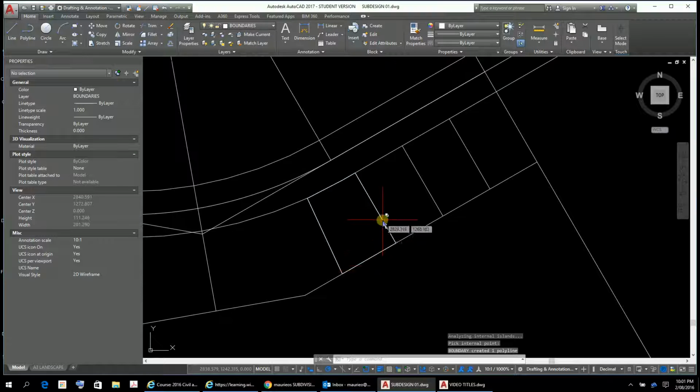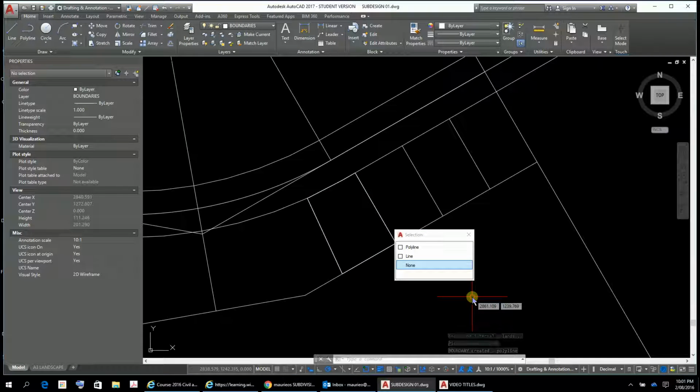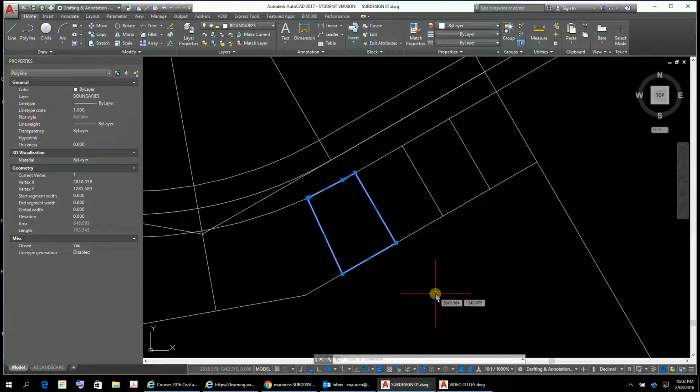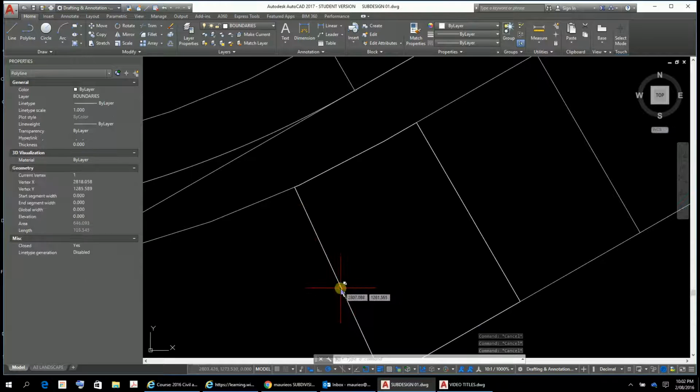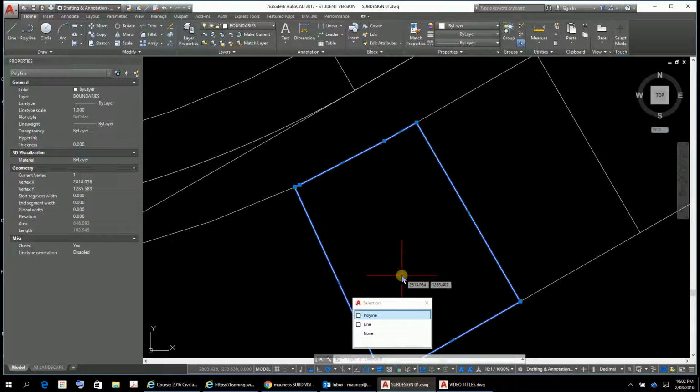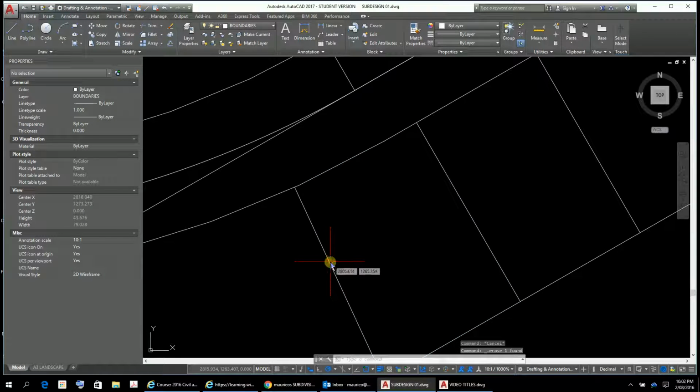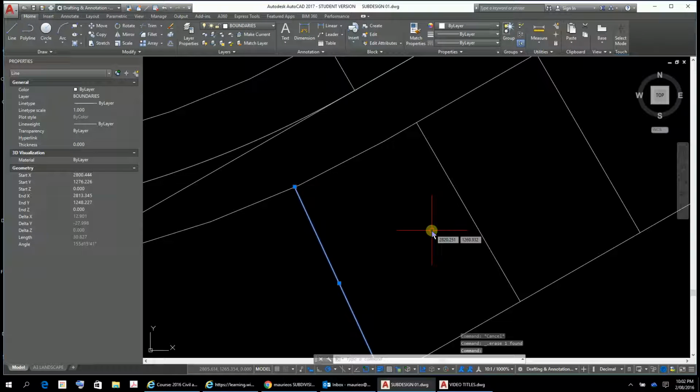And then if I select that polyline, over in my properties, I can see that that's 646 square meters. Now I'm going for 600, and there's a little extra 50 in there. I'll just take that polyline out for now, just delete that there. This line here is approximately 30.827, and we had 646 there, so that's 46 extra.